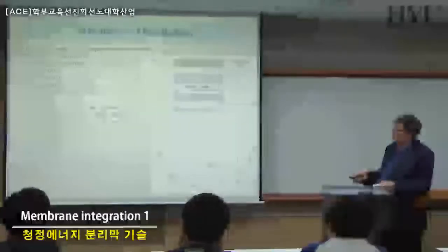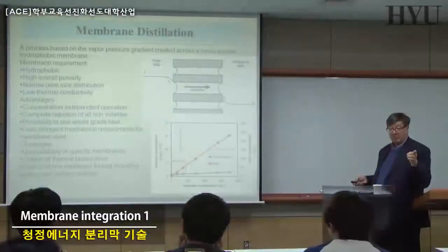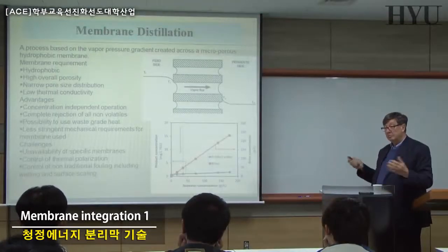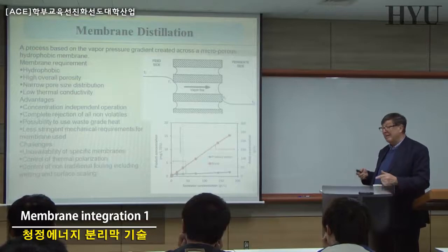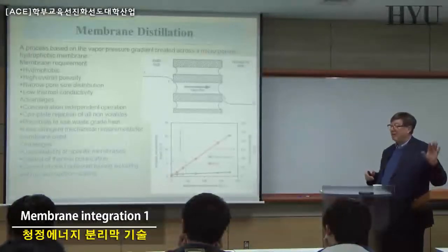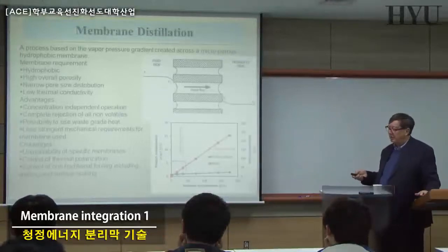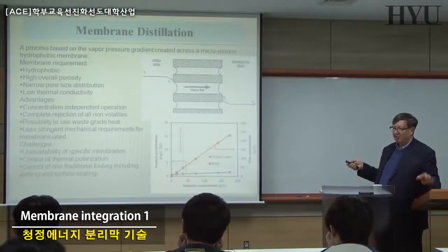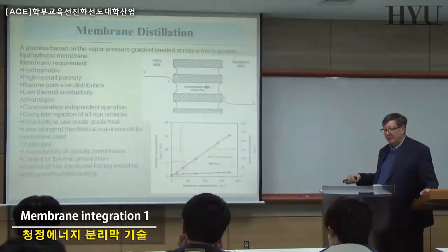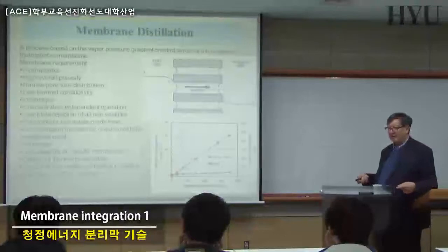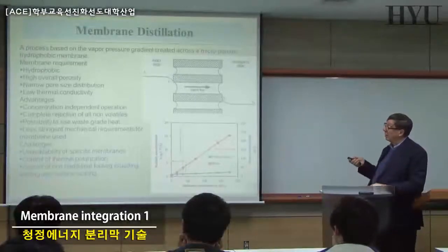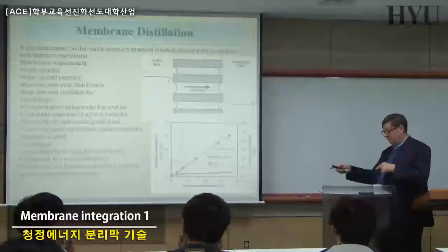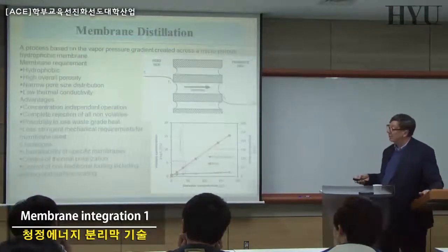But these new membrane operations mean membrane distillation. Just to remind some of you, membrane distillation is a way to solve problems, as we are mentioning, but we need totally different kinds of membranes. Membrane distillation has nothing to do with traditional reverse osmosis or ultrafiltration. You have to develop a microporous hydrophobic system in which only vapor goes across, no liquid phase. So you have to find new kinds of materials, not traditional aromatic polyamide, but strongly hydrophobic materials that can be produced in hollow fiber or flat sheet configuration, but microporous and hydrophobic. If you do this, you can solve the problem and well spend the 70 millions that I was showing before.